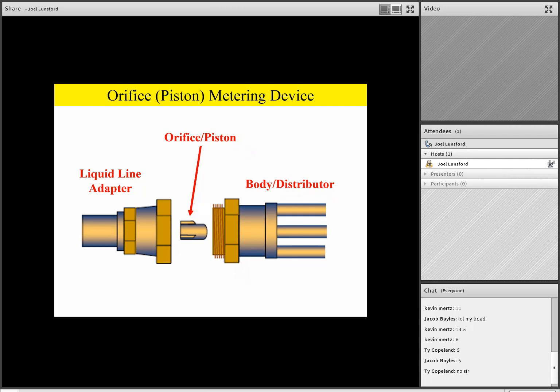So remember, again, on an expansion valve, it should maintain approximately 10 to 15 degrees of superheat. In addition, from a charging standpoint, the expansion valve will always be used with a subcooling type of charging. Subcooling for charging with an expansion valve. However, on the piston type of metering device, we're going to have to utilize a chart, a superheat chart, to charge it properly with a piston.